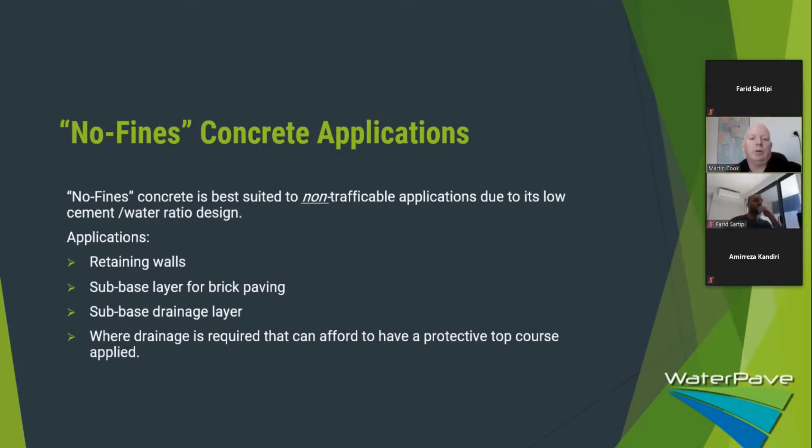So yeah, no fines concrete applications. No fines concrete is best suited for non-trafficable applications due to its low cement water ratio design. It's mainly used for retaining walls, a little bit behind retaining walls, to allow the water to egress down the back of the retaining wall rather than pushing hard up against it with hydraulic pressure.